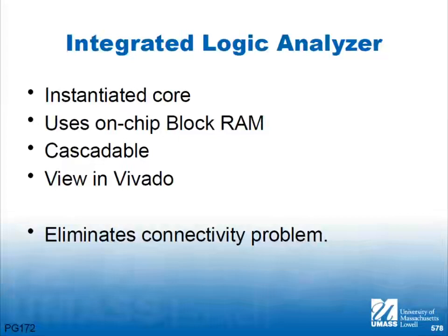The software for this comes with the development tool. So it's not a $50,000 logic analyzer. It's free, but the $50,000 logic analyzer has more memory, and more memory gives you more depth of trace and more signals to trace. So we're going to be a little limited in both of those, but you don't need 512 connections, which you would get on that expensive logic analyzer. And then you look at it in Vivado, which is going to be another important selling point. Okay, so no connectivity problem.